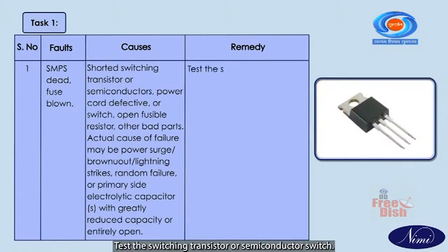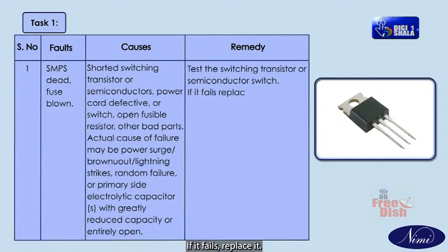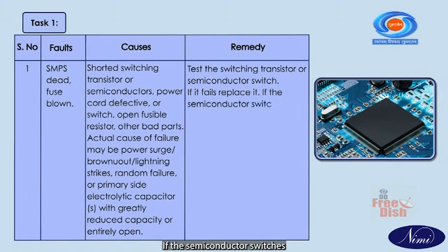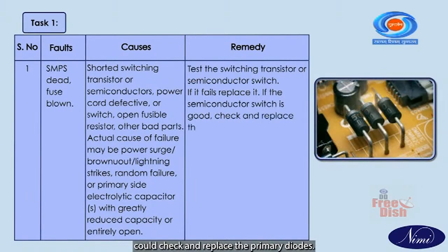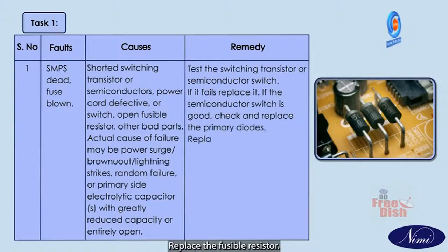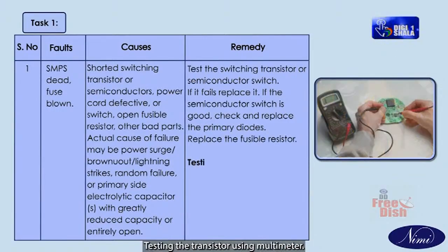Remedy: test the switching transistor or semiconductor switch. If it fails, replace it. If the semiconductor switch is good, check and replace the primary diodes. Replace the fusible resistor. Testing a transistor using multimeter.